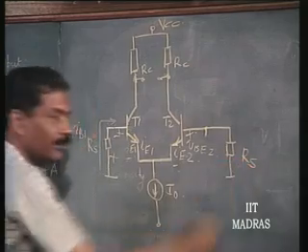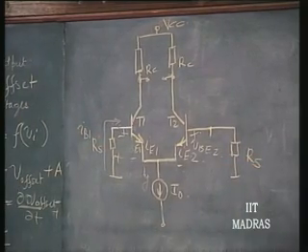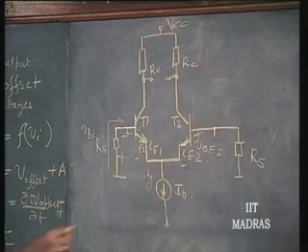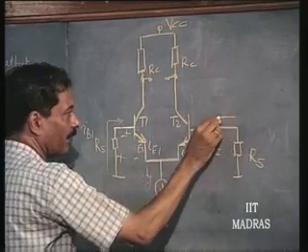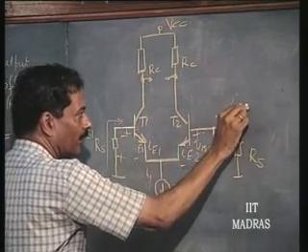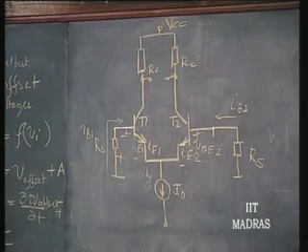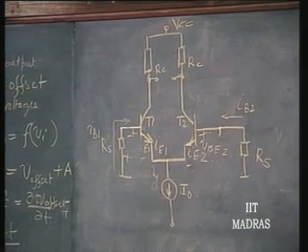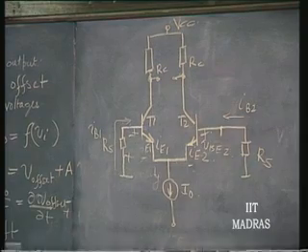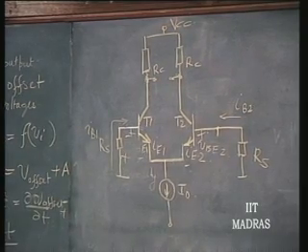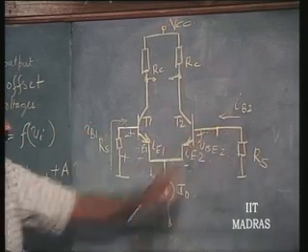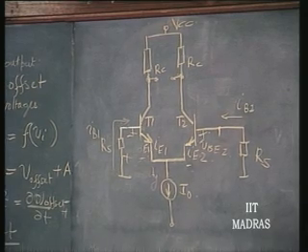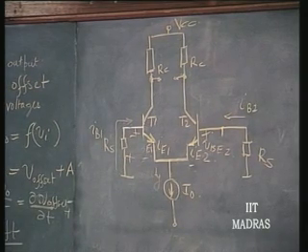One way to tackle that easily is to connect another RS. That solves your problem partially, because unfortunately even if the transistors are very well matched, the betas need not be exactly the same, and IB1 and IB2 may be different. So even if you put equal resistors, there may be a resultant offset voltage due to IB1 minus IB2 not being equal to 0 for the same emitter current.